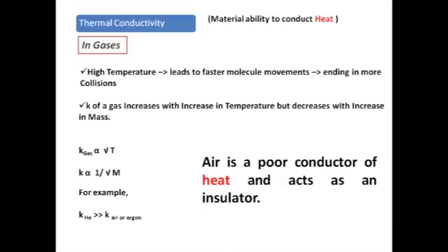In a thermal power station also, before we supply water to the power plant, we treat it. We deaerate the water and we remove the air completely. Otherwise, the presence of air in the water makes it less thermal conducting and it arrests the heat transfer from hot gases into the water in the boiler, and it restricts the condensation also in the condenser.